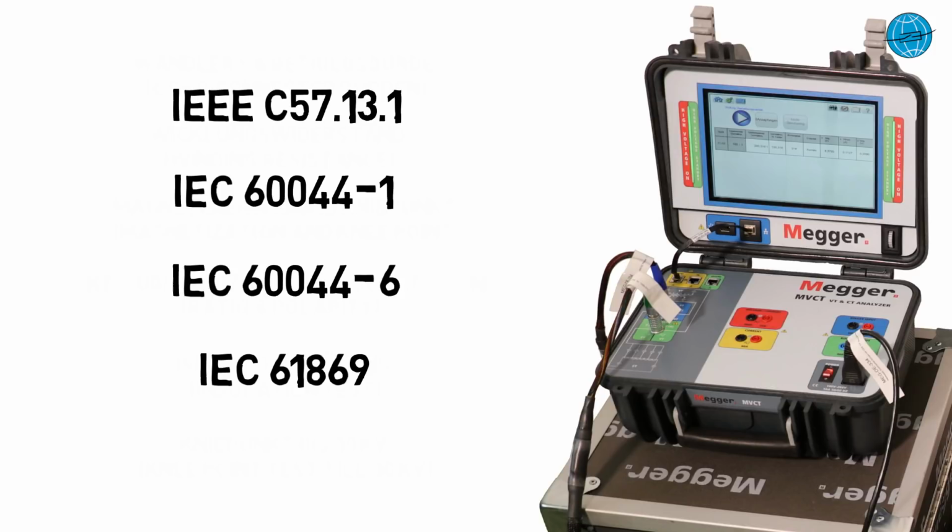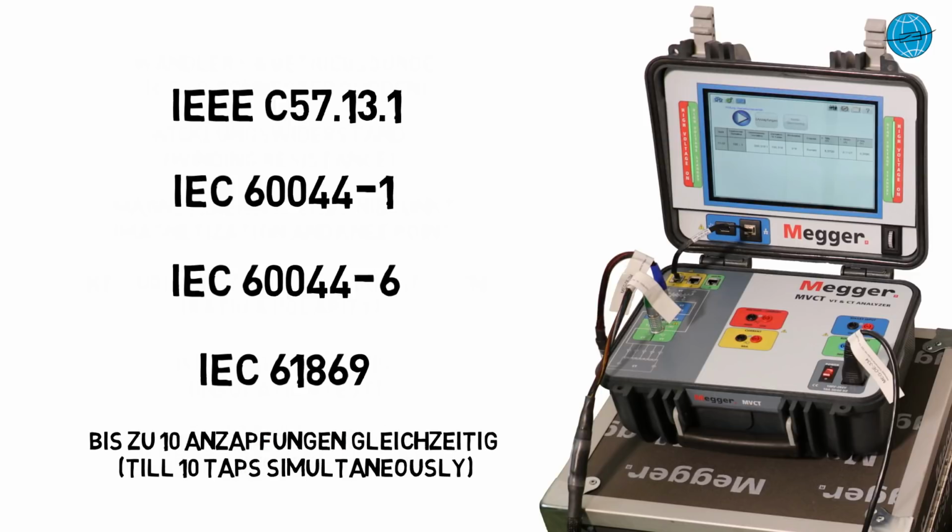While the saturation test is being performed, the MVCT records the CT saturation curve on the STVI display and provides the nominal knee point according to the desired standard. Since current transformers sometimes have multiple taps, the MVCT has the ability to record and display up to 10 CT saturation curves at the same time.